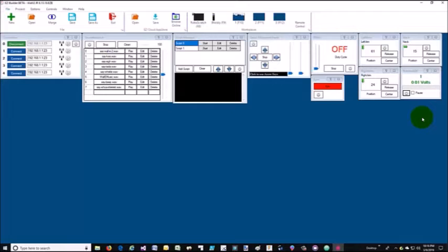And I'll try and share with you later on the circuit I used for this, because there are two switches interconnected and then a set of different resistors, so as you press the switch, it sends a different resistor value down to the ADC line. It'd be the equivalent of hooking up a potentiometer to the ADC line and adjusting it up and down.